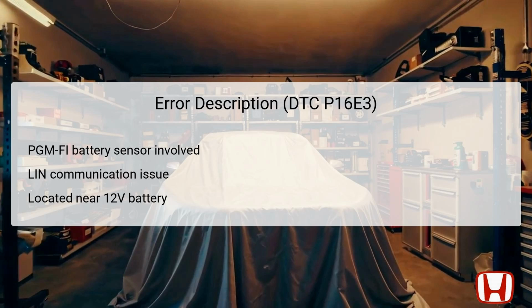The battery sensor plays a crucial role in ensuring accurate readings of the 12-volt battery's voltage, which is vital for various electrical systems to function correctly. It connects to the vehicle's local interconnect network, LIN, for accurate data transmission to the engine control unit. This sensor is located near the vehicle's 12-volt battery. When there is an error, the engine may not function optimally, as it may lack real-time battery condition data, which can affect the vehicle's performance and lead to battery-related issues.